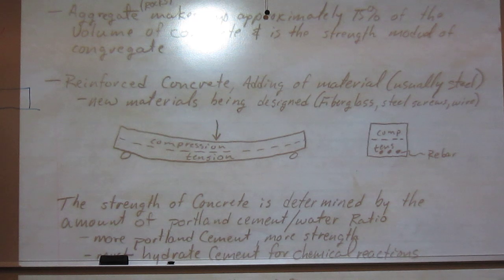Now I've got a weight, let's say of a house, so it's a continuous weight. There's my free body diagram. What's going to happen where that soil has settled out underneath my concrete? It's terrible in tension. In fact, it's so bad in tension we don't even calculate it.